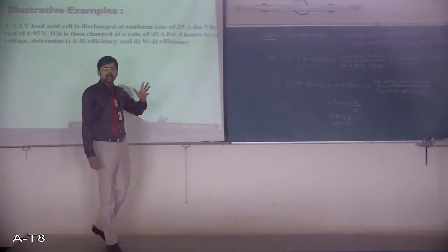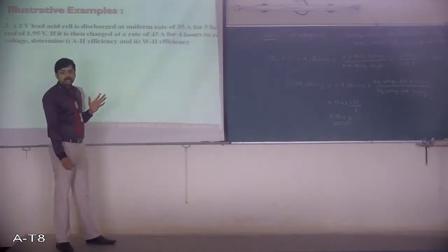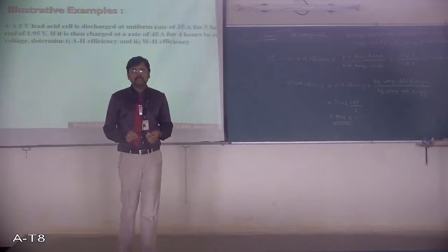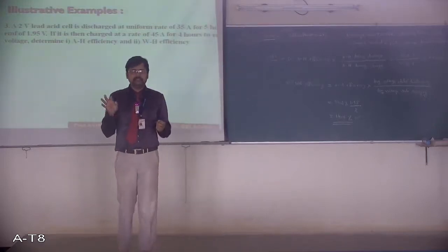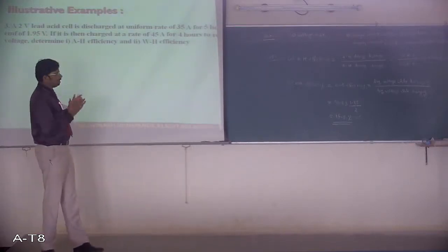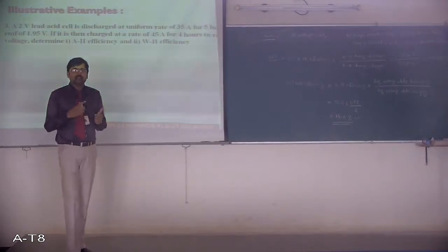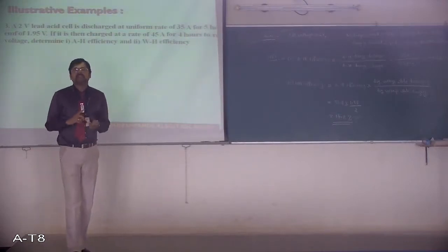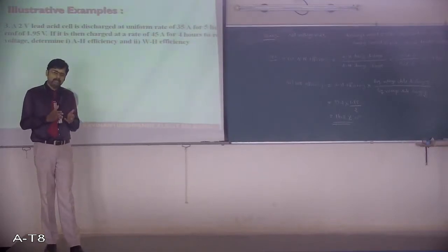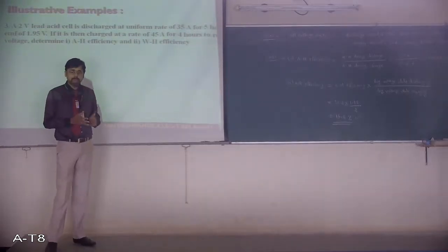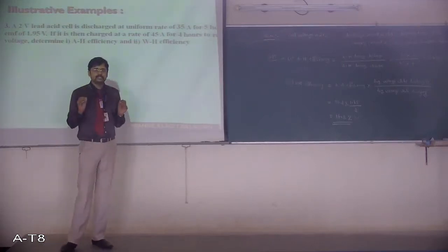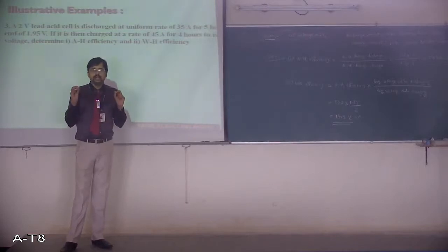All these are engineering tasks that are involved. Anyway, it's an introductory course, so we cannot go into detail about the lifetime of the battery. It covers some basics related to the UPS system: how to design the UPS system, how to select the rating of the charger, the rating of the inverter, and how to select the battery system. In that battery system, how to select the size of the cell, voltage rating, power rating, and how many jars are to be there. That means how many cells are to be connected in series and how many in parallel. Everything we discussed through these 3 illustrative examples.